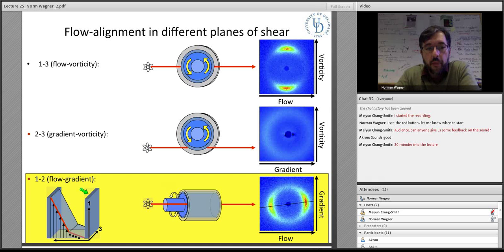That's very important. One reason that's particularly interesting for me and my research group is the fact that you can get shear banding flows, where the flow field is not homogeneous. It actually breaks into 2 or more different distinct flow regimes, and as I'll show you, you can access that information only in that 1-2 direction. The others average over the entire flow field.